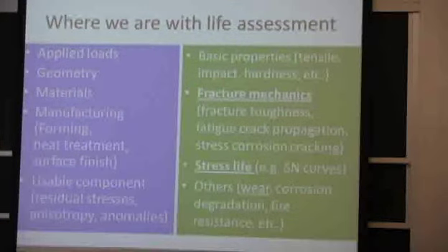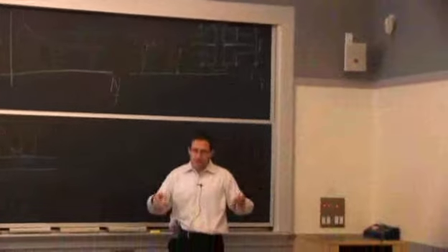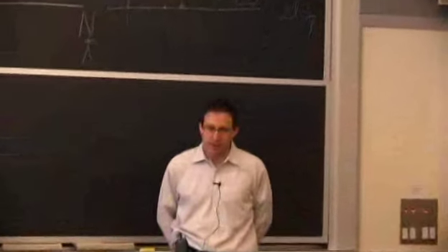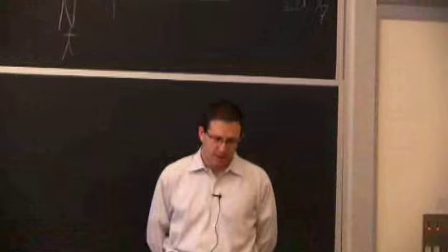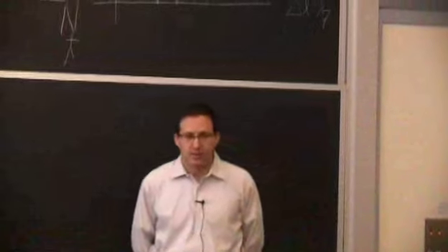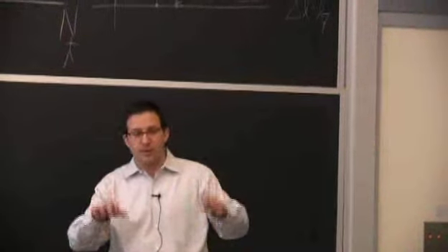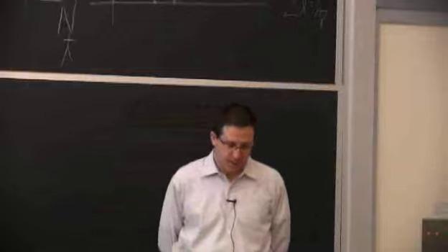And Professor Eager is going through forming, but as part of manufacturing, there's also heat treatment that we talked about a little bit, quenching and then heating up for aging, for example. We talked a little bit about annealing, which is to essentially soften the metal.